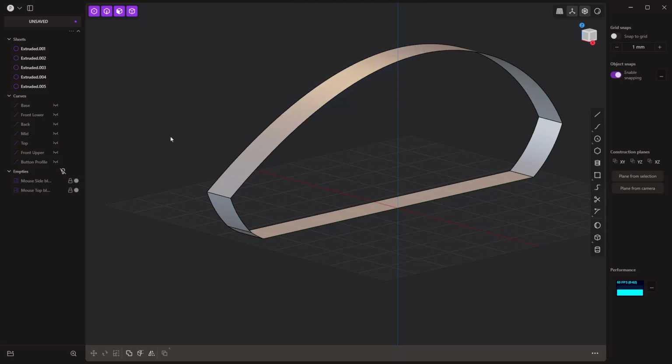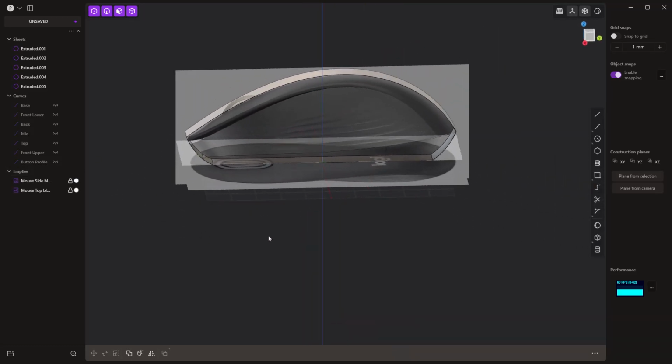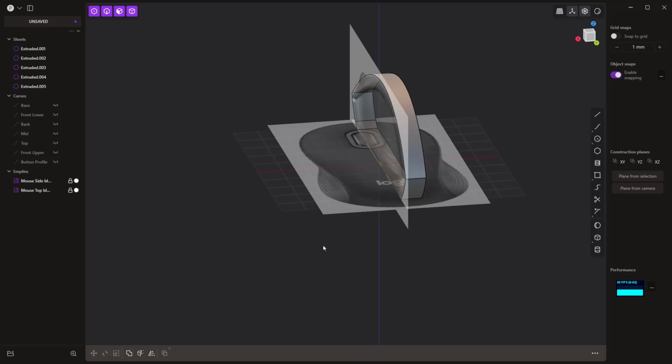The xNurbs tool is only going to be in the studio license version. You can still do everything that we're going to do here with the loft tool if you want. There are some nuances and exceptions, differences between how some of those tools work, but we are going to use the xNurbs tool because it does give a little bit better surfaces in most cases, not all cases, some cases they're identical. Keep in mind that if you are using the loft tool, you want to make sure everything stays connected. Your loft guides and your rails have to have continuity with each other. So that's something that the xNurbs tool can kind of get around.